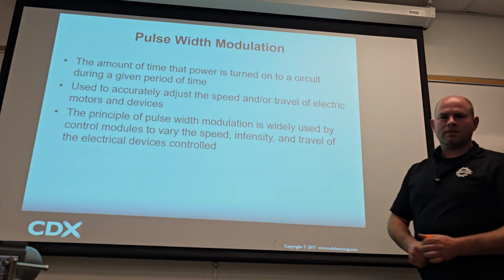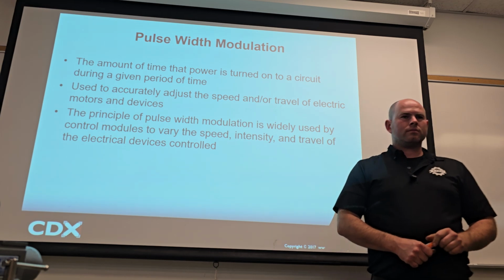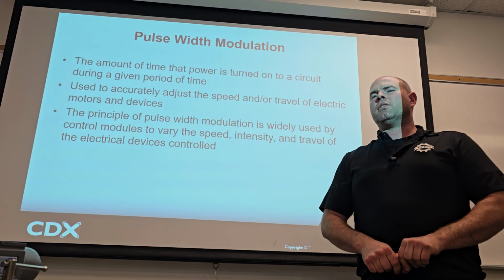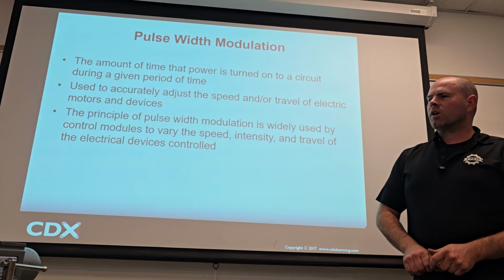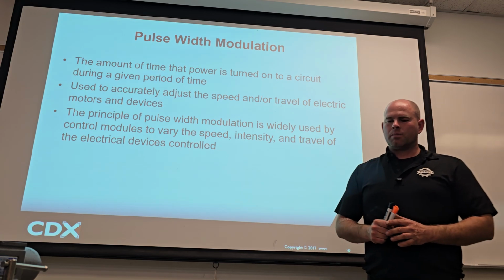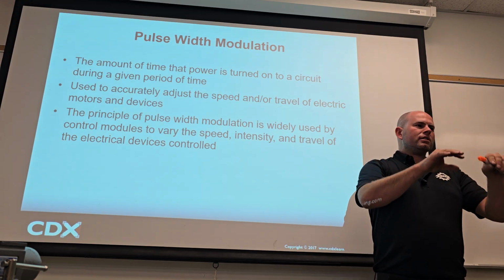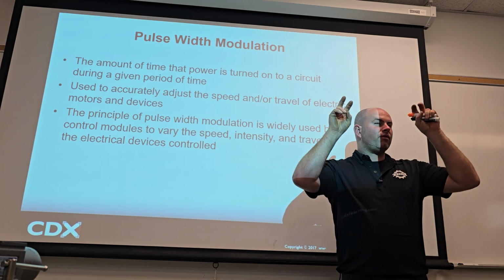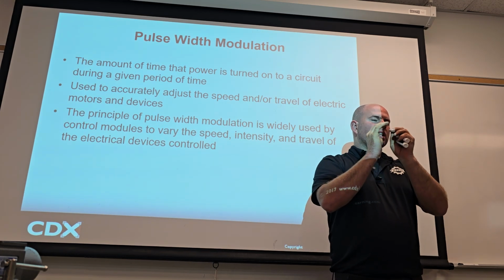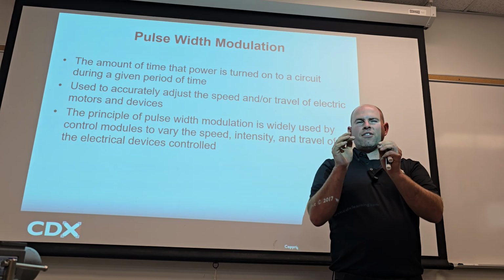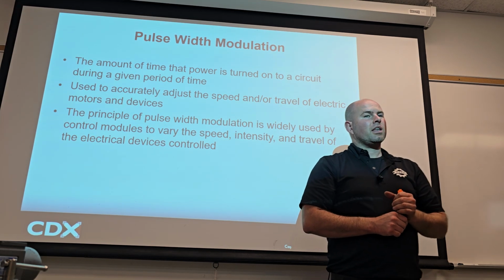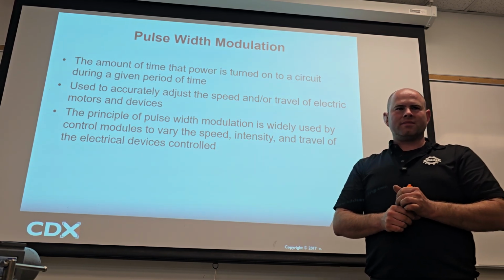Paul, when you say use a scope, are you talking about using the scan tool scope or the actual scope? That's a good question, and we're going to cover scopes specifically, but in one second I'll go back to the picture. If you go on the scan tool, you can do the scope function, which is more like looking at the information in the computer and putting it in a graph for you, but it's not the actual measurement. So it's not the actual sample signal. It just gives you the shape of it.